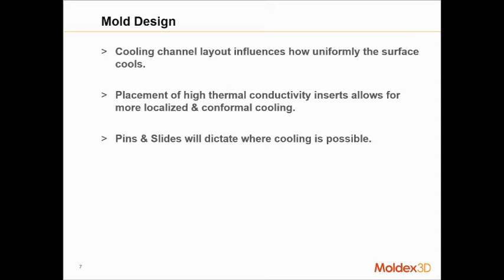But the closer you can get your cooling channel system to be exactly on the surface of your part, the more uniformly your surface is going to cool down. And we'll explore in a few moments why that's important, because we actually have 2 zones of temperature that we're trying to influence. So the cooling channel layout is going to influence really what's happening on the surface of the part.